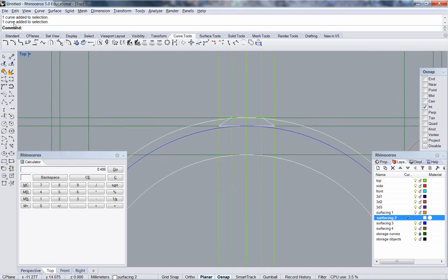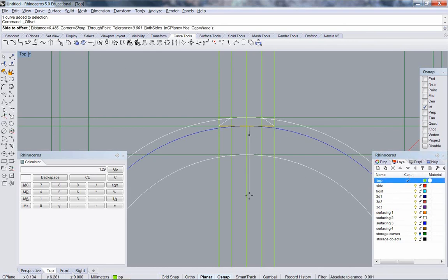Okay? So, pavilion depth is 0.431. I'll just go to 2 decimal points this time. So 3 times 0.43 is 1.29. Offset a construction line straight down, 1.29 millimeters. Typed it in here. Click. And now I can draw the pavilion of my stone.